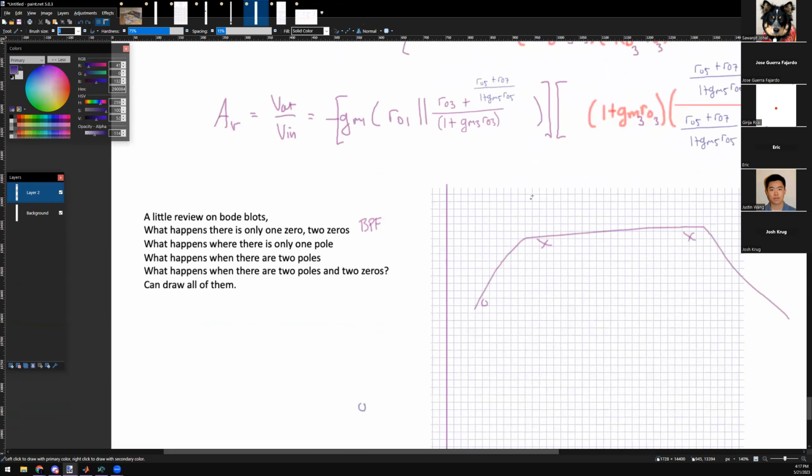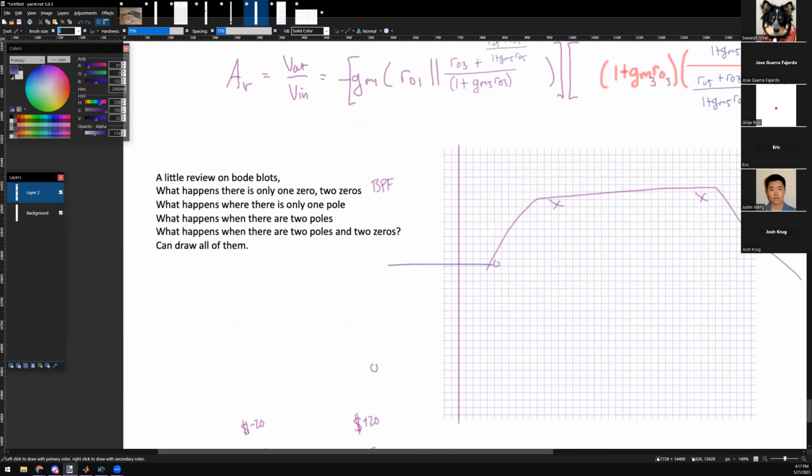Yeah, that was my initial question. What happens when you have a transfer function like 3s plus 1? Or 3s? Yeah. With 3s, you have a zero at zero, and you just have a differentiator, and you always are positive 20 for your entire life. Okay.